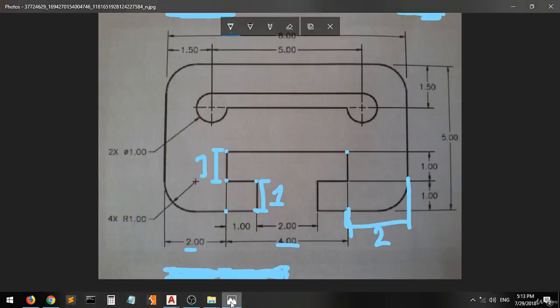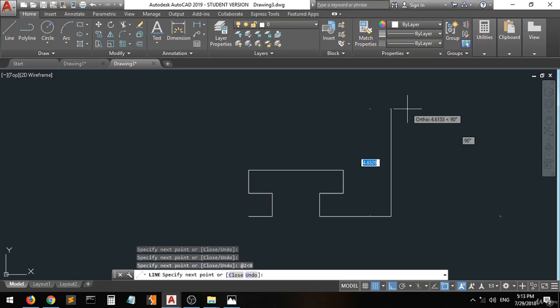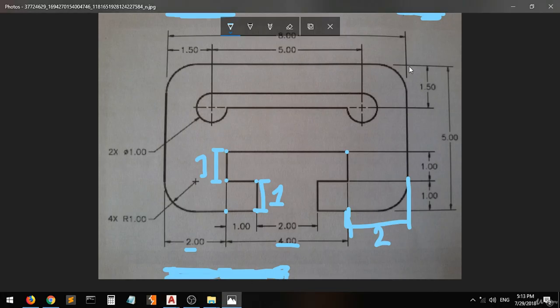Excellent. Now going back to the drawing, we will move what? This whole distance, which is 5. As we said, we will create it with pointed head, then we'll create the fillet shape, okay? Don't forget this. We'll create it as a simple rectangle, then we'll do the fillet shapes, okay? Now we'll move up at 5 in the direction of 90, enter, and then this whole distance from here to here, what? 8.